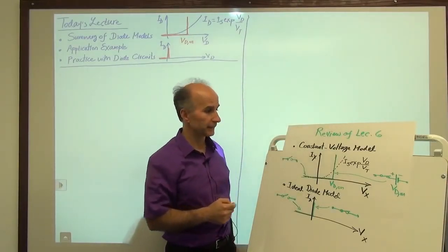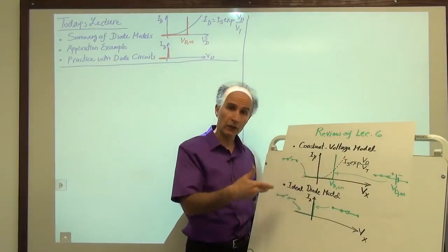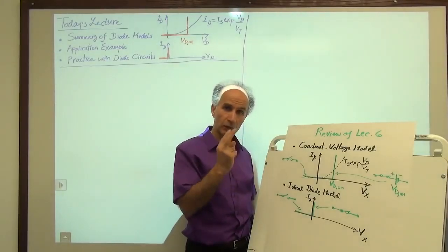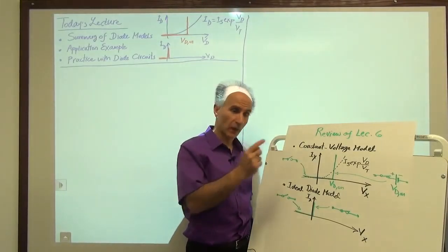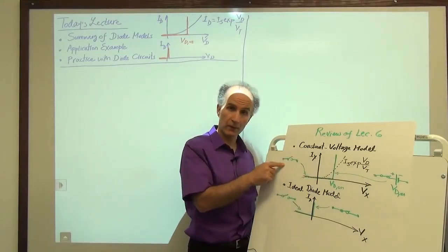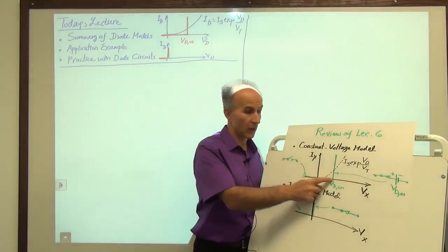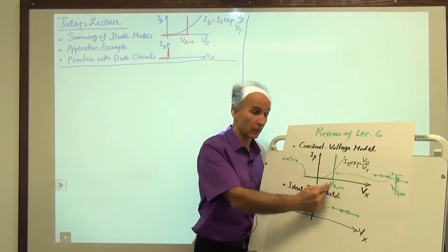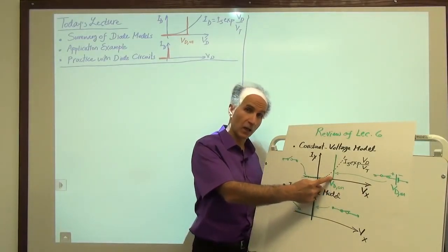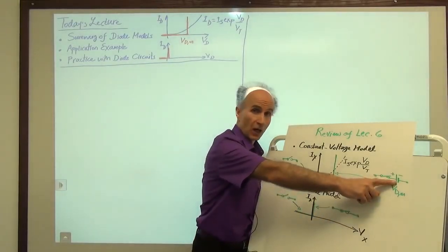With the constant voltage model, our electrical representation of the diode consists of two different possibilities. If the diode is off, it has no current, so it's just an open circuit, like a switch that is turned off. On the other hand, if the diode is on, at a voltage of VD on, then it is like a switch that is turned on, but in series with a voltage source of value VD on.